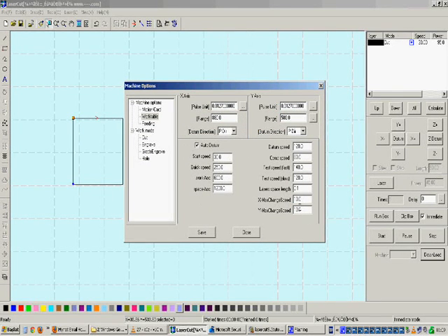On the menu below, you will see some speed values. The first one is the start speed. Start speed is the speed of the laser machine head while starting a cutting operation. Bigger values will cause the machine to start cutting operations with higher speeds, so this will cause some impact on the machine head. So too big values are not advised.